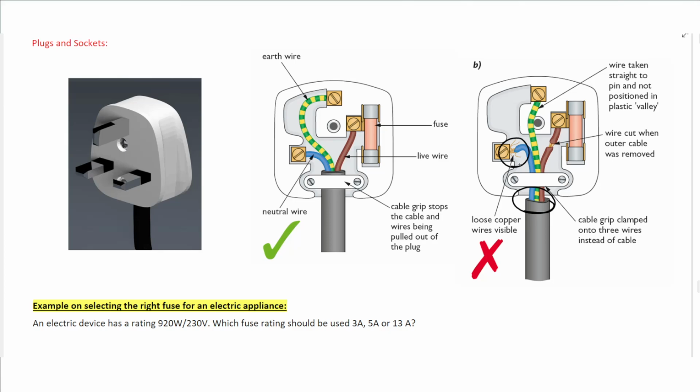If you use a fuse, you must know how much current it can take. So for example, if you have a device that can take up to 4 amperes and the connecting wires can take up to 20 amperes, the wires can take much more current, so you are not worried about the wires, you are worried about the device. The device can take 4 amperes, so you must decide on a fuse that does not allow current to flow much greater than 4 amperes, even though the wires can take 20 amperes.